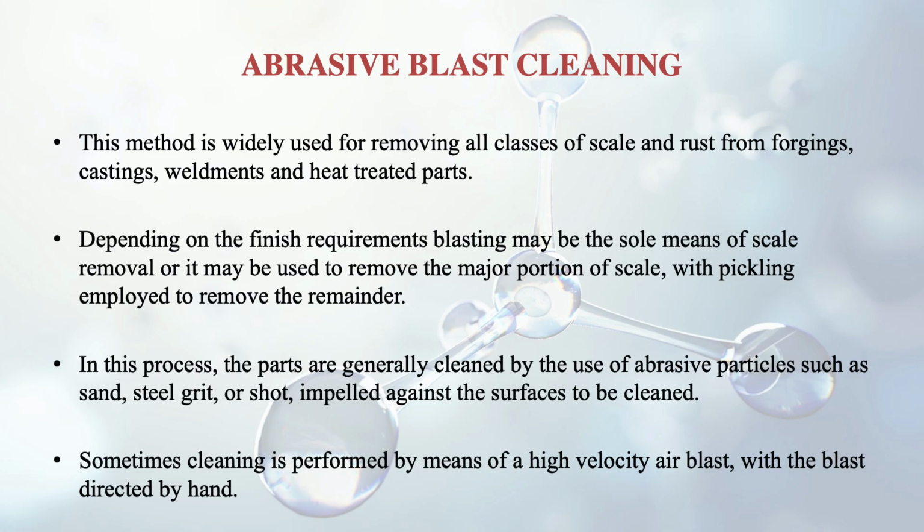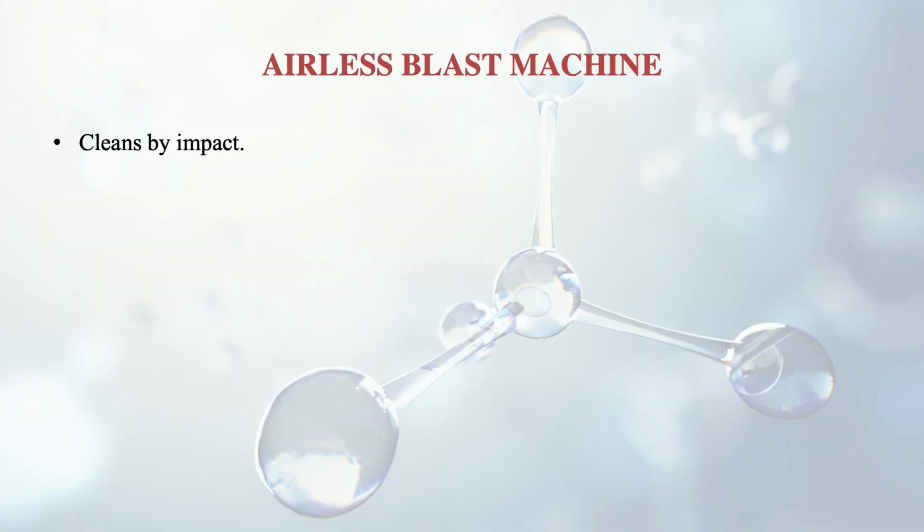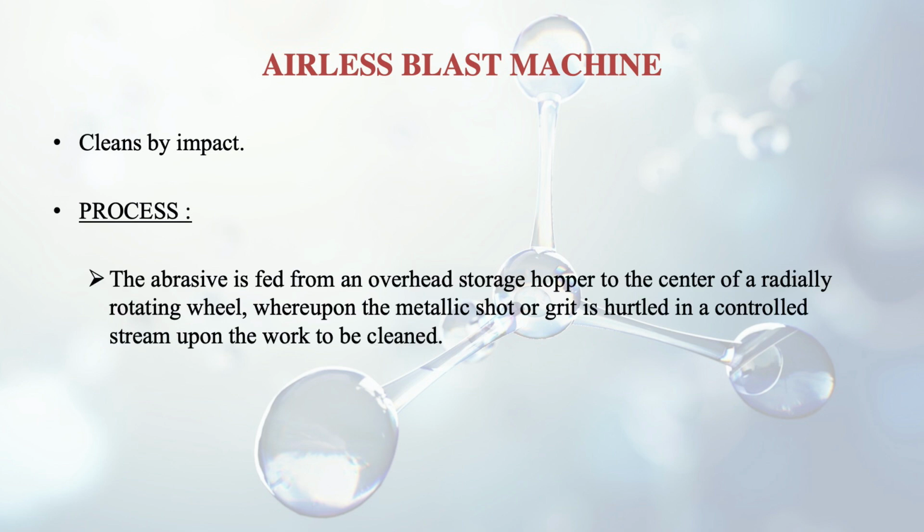Air blast is also there, and blast is generally directed by the hand. And then there is one more thing, that is airless blast machine. So in addition to the air one, we have airless one also. So this one also cleans by impact, and the process is as such: the abrasive is fed from an overhead storage hopper to the center of a radially rotating wheel.